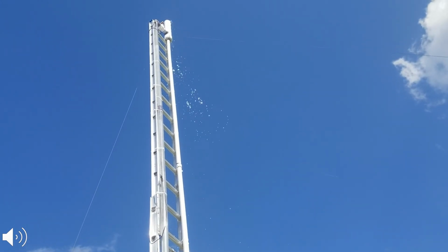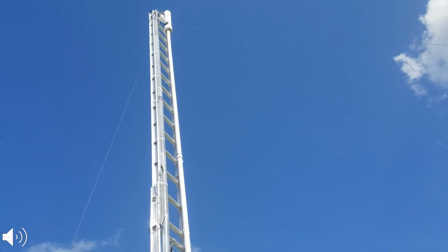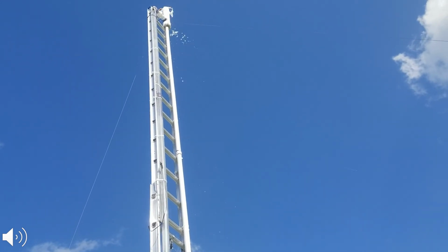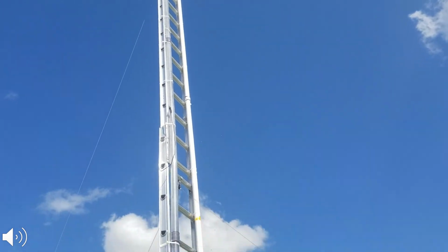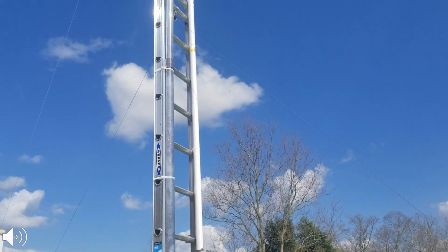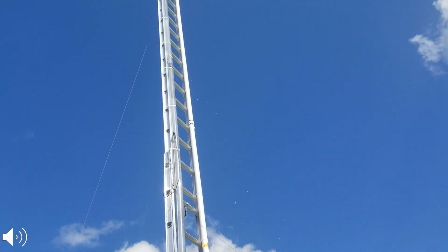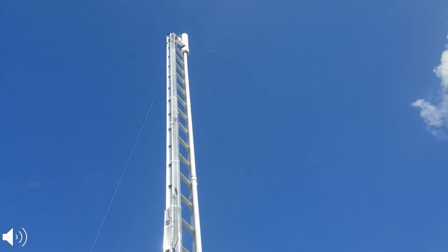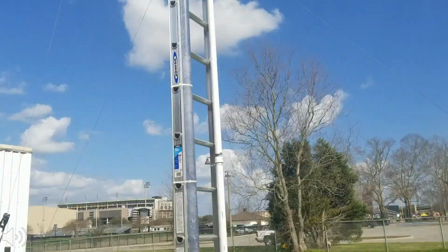Similar to the bench model, there is an actuator control valve at the top. The entire model is powered from a 120-volt AC system that is reduced for the control module and transducers to 20 volts DC through an AC-DC converter. The constant airflow is supplied by a 1 horsepower, 15-gallon tank air compressor.